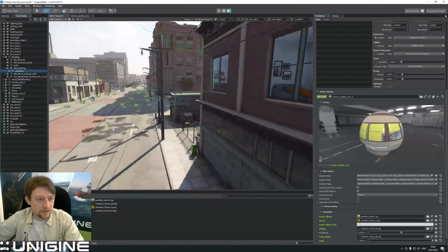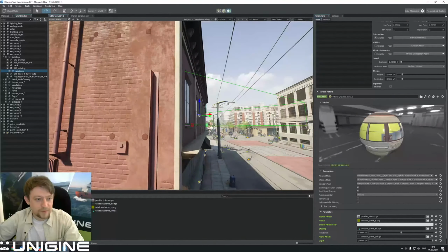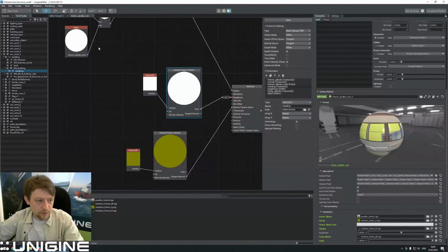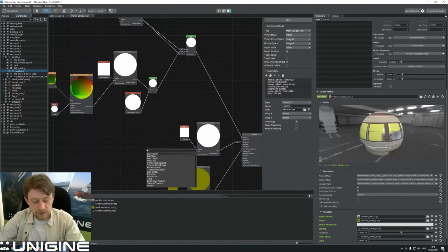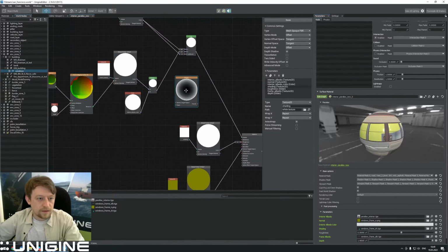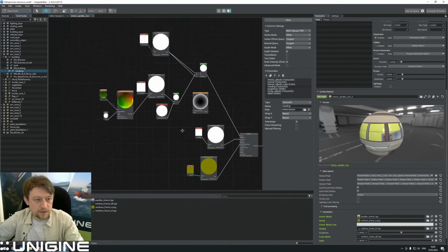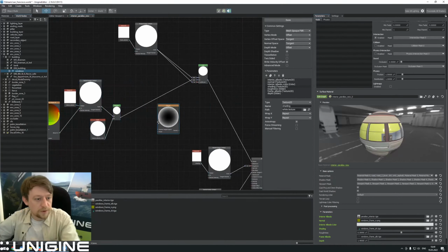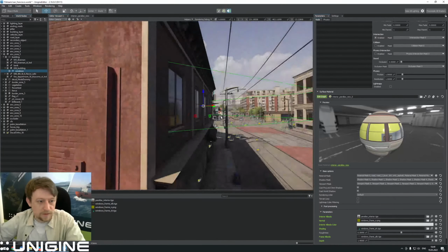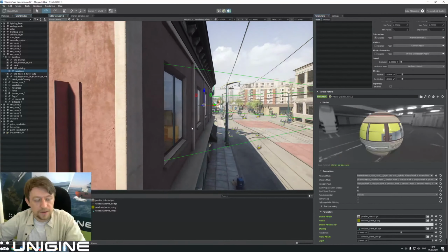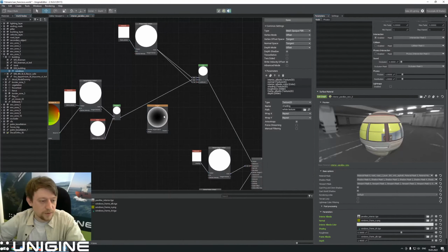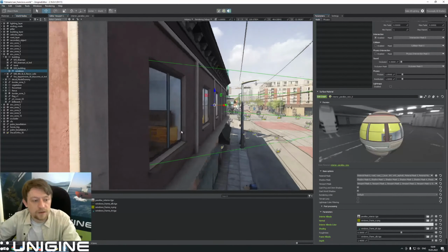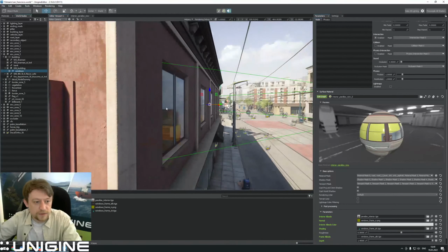And to fake the effect of the darkness in the room, we could use an additional subgraph which is called Fresnel. So what we want is we want the interior to be darker at the sharper angles, like here, right? So the Fresnel will just give us the mask depending on the angle between the vector of the camera and the normal of the surface of the glass.